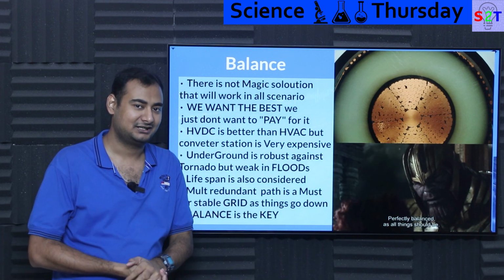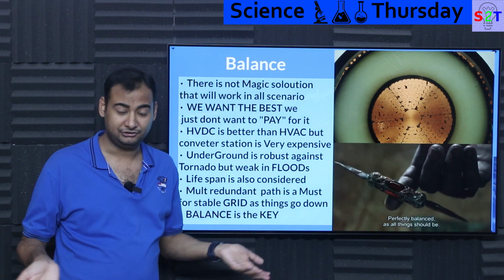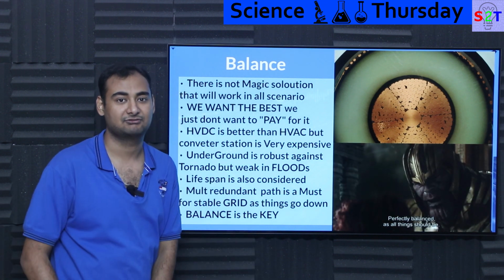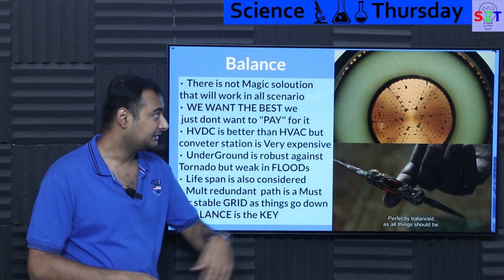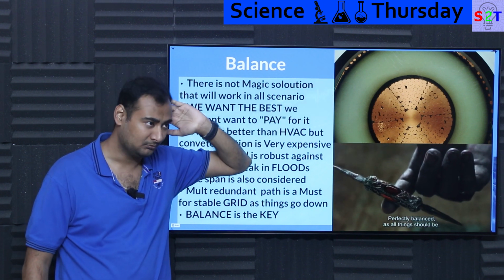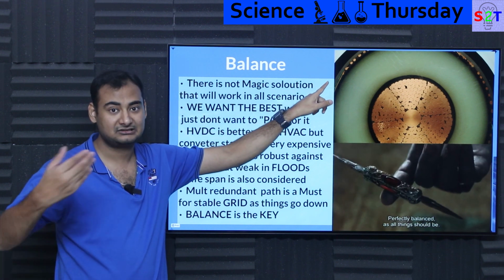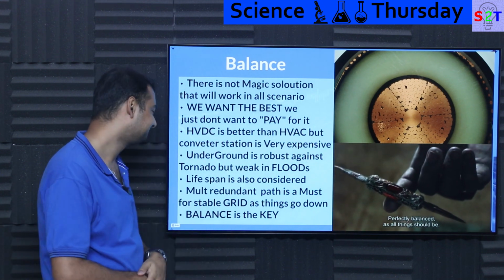How do you see which part of the link broke in an earthquake, in a flood? You don't. You have to study every single cable vault. Is like, hey, I think it's working from here to here, or put sensors throughout the link. Again, HVDC does have a fiber intermediate, because the cable is so expensive. It would be much wiser to invest extra cost just to have fiber throughout the line, so you can figure out where the cable break happened.